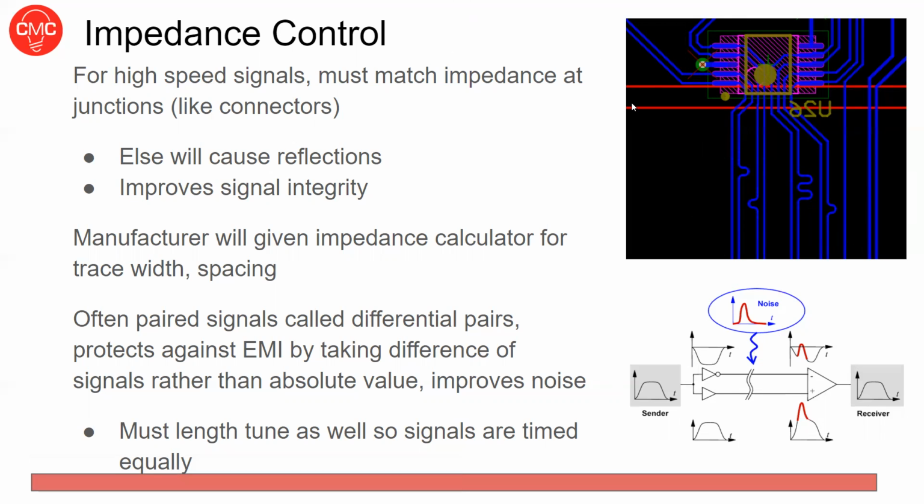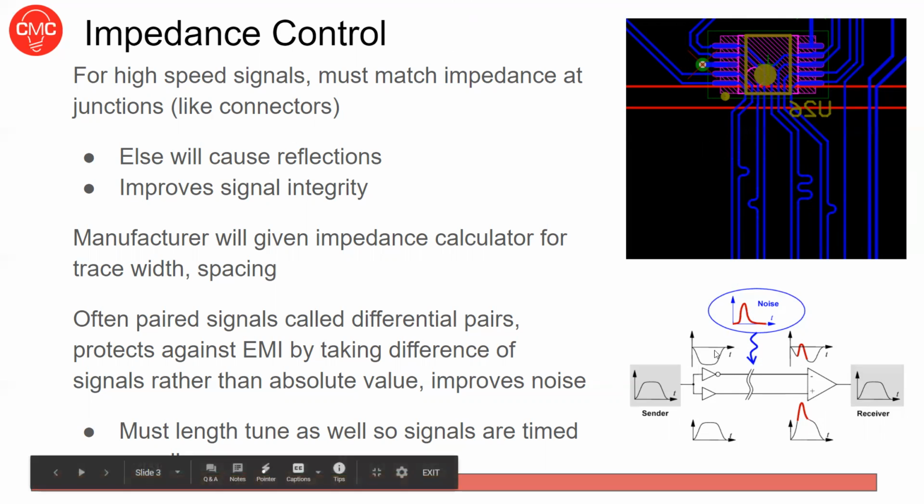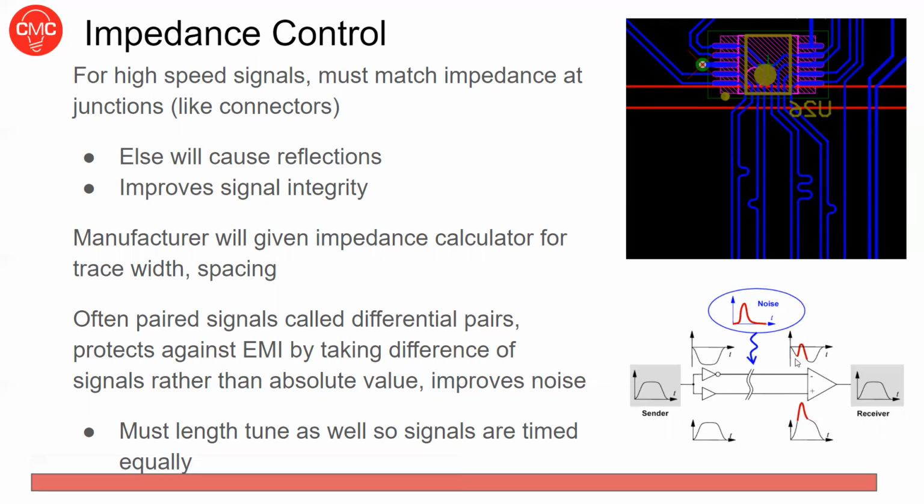around other chips and throughout the board, and you have any kind of noise spike, whether that's interference from a different signal or something like that, it could change fundamentally. So let's say this would be a 0 and then it goes to a 1 and goes back to a 0. But here, if you add this noise to it, it goes 0, 0, 1, 0, which is not what you want. And then if you read the signal on the other side, you would be reading the wrong information.